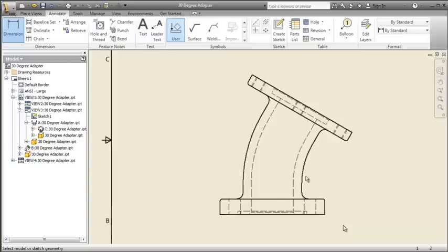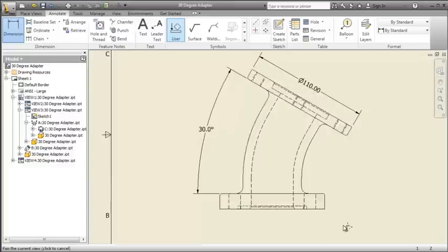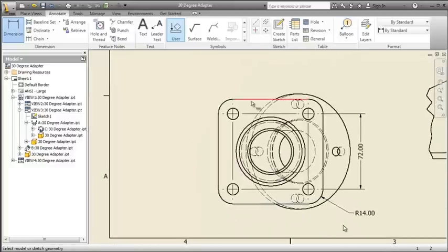If I come up to this front view, I can start placing a dimension, but if I come near this angled edge, it shows me that I can place an angular dimension. Or if I pick the side of this cylindrical edge, I can show a linear diameter, all from the same dimensioning tool. Now, there are times where we may want to create dimensions more rapidly.